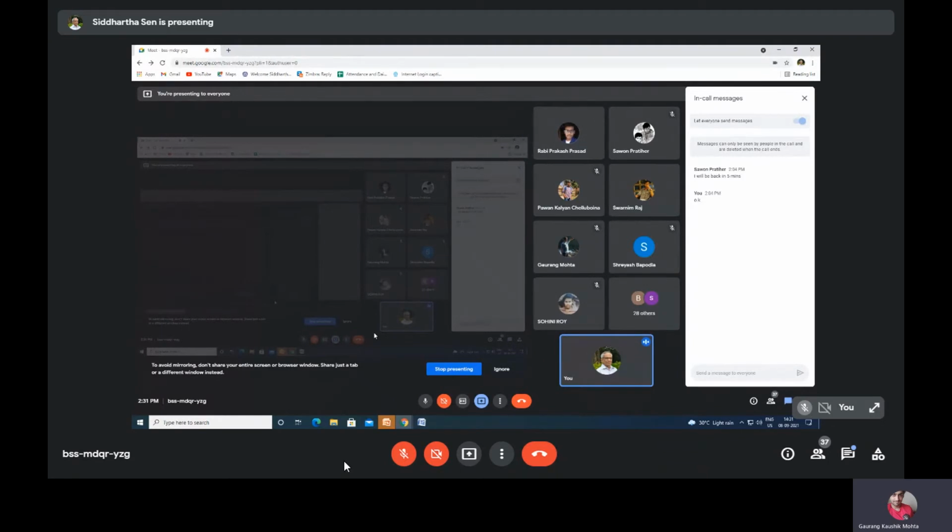Okay, sir. Any other questions? Hello, sir. Yes. Sir, I have done the whole signal conditioning circuit for the previous experiment in LT Spice, and my range is from 100 degrees Celsius to 200 degrees Celsius. Whenever I'm sweeping the temperature from 100 to 200 in steps of 5, it is able to converge the results in all the places. But let's say I'm taking a temperature of some random like 167, then it is not able to converge the simulation. For some reason, I'm not able to.